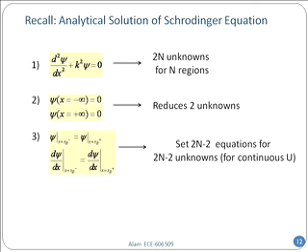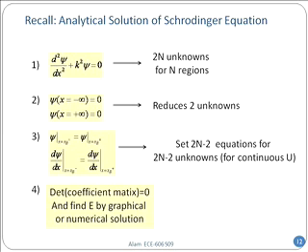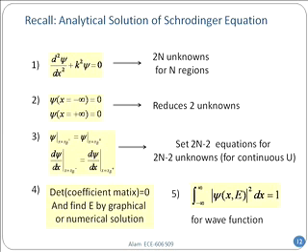Then there was all this continuity relationship, right? Do you remember? That allowed us to stitch up the solution from one side to another. We'll do the same here. The 3 regions, 1, 2, and 3, like in the last one, we'll stitch up the solution at individual interfaces, and that will give me the global solution. Now, there is no equivalent of 4 and 5, but that's all right. We should be able to get up to 3, and then that should give us the carrier concentration profile.